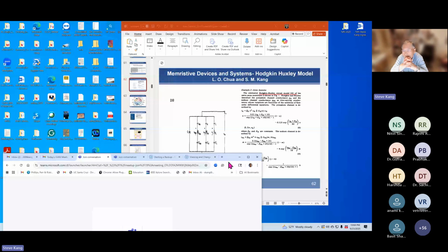But the memristor itself, its merit is like a crossbar array, where you have a very simple structure of interconnect and so on. If you use a mem transistor, its interconnect becomes a little more complicated. On the other hand, to prevent some leakage current, you need a MOS transistor, so you have a 1T1R type of configuration, which requires an additional terminal.